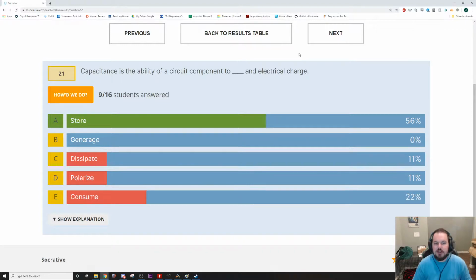But it's not great because capacitors do discharge while they're sitting. If you're just going to jump the car off and drive 500 miles in a circle, you don't really care that if you park it, it won't start next time unless you jump it off. You can just charge the capacitor up, crank the car, and go.